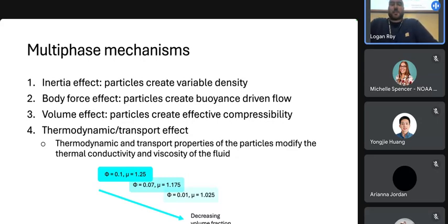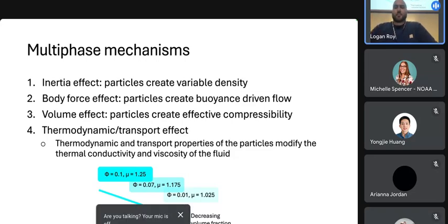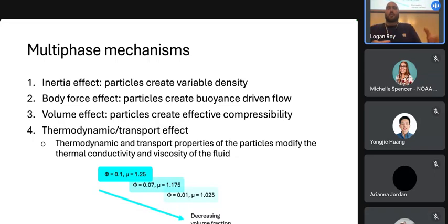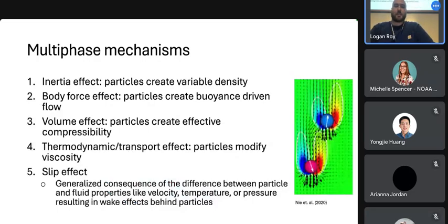So this is a consequence of including some of the additional boundary conditions that you get out of particles in your dynamic system. Those additional boundary conditions result in a modification of thermal conductivity and viscosity. So here again, we've added particles and now we have this viscosity dependence on particle volume fraction. That's really tricky to deal with and leads to some interesting consequences.